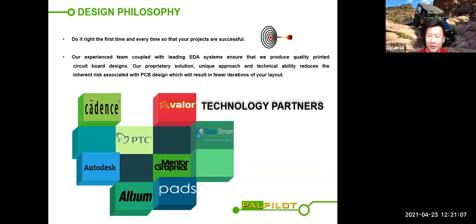You can do anything on the layout, but can today's manufacturing capability actually produce a PCB that small? So design for manufacturing is wrapped around this idea. You want to do the design, but you want to make sure 90% of the factories in the world can build it, and you can build it inexpensively with a very good yield rate.